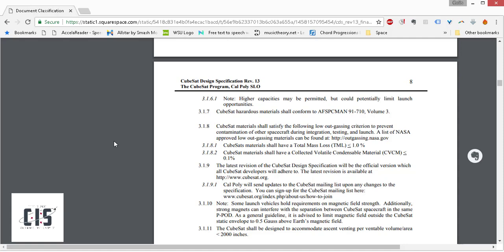And the real concern is that some of those are going to either create a cloud of mist that can damage solar panels, or recondense onto other stuff. Usually solar panels, and then solar panels don't work as well. They especially like to condense on optics and anything that's cooled. A lot of really high tech camera systems or optics are cryogenically cooled, so they're very cold, and stuff condenses back on. So you're like, there goes my pristine picture. Yeah, so that's why we want to be careful with outgassing.